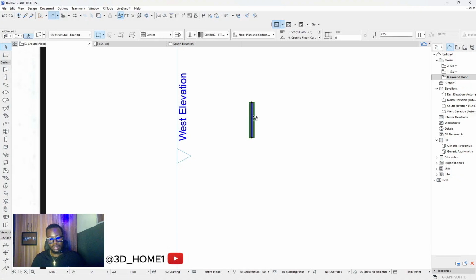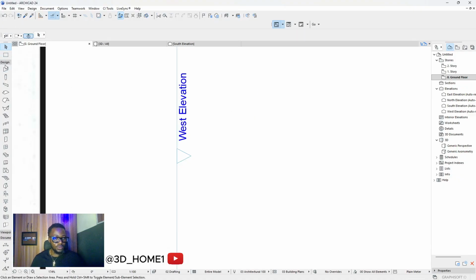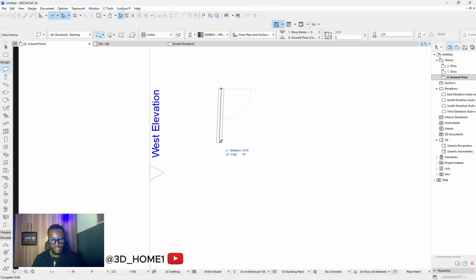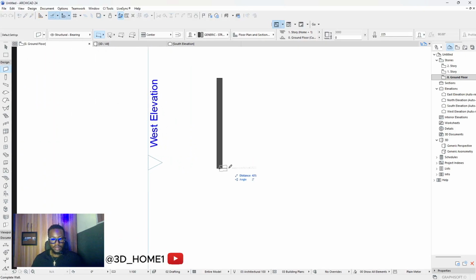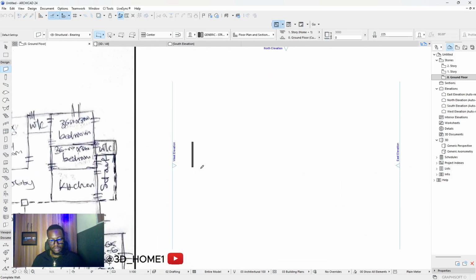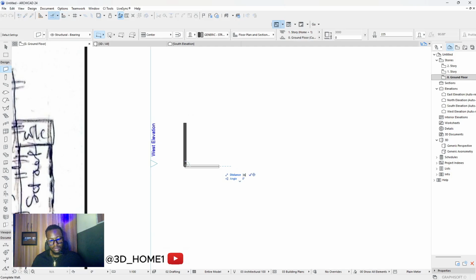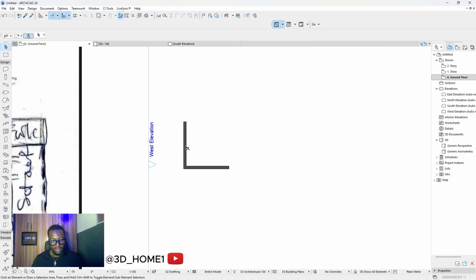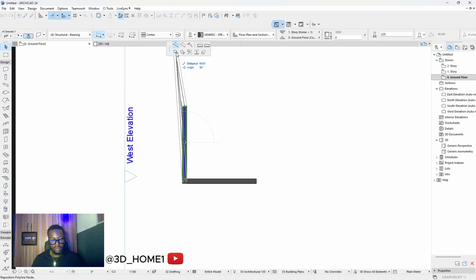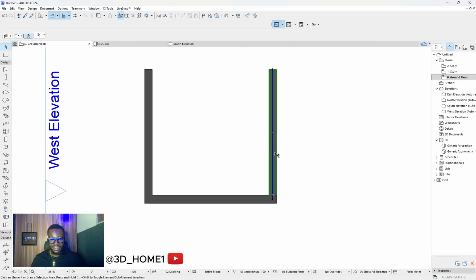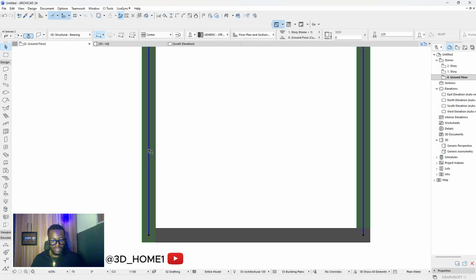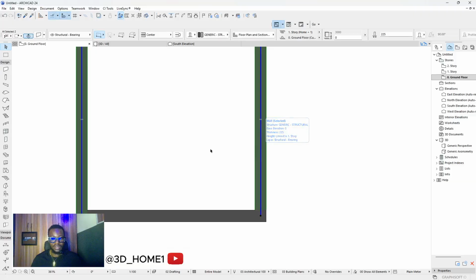So what we're going to do right now is, mind you, we're working with center line. So I'll click from here and then I'll type 3,600, enter. And same thing, since everything here is 36 by 36, so I'll select 3,600 to here. Now this time around, pick here, click on this, drag, tap control to have the plus sign. Let's type 3,600. Mind you, this is center to center. So that means from this center line to this center line is 3,600.